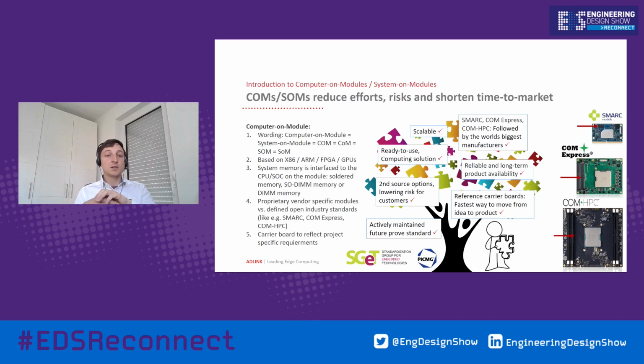Computer on modules are always required to be mounted on a carrier board, which breaks the module interface out to standard peripheral connectors, since computer on modules and system on modules lack the standard connectors for any input and output peripherals to be attached directly to the board. And this is basically the clue, right?